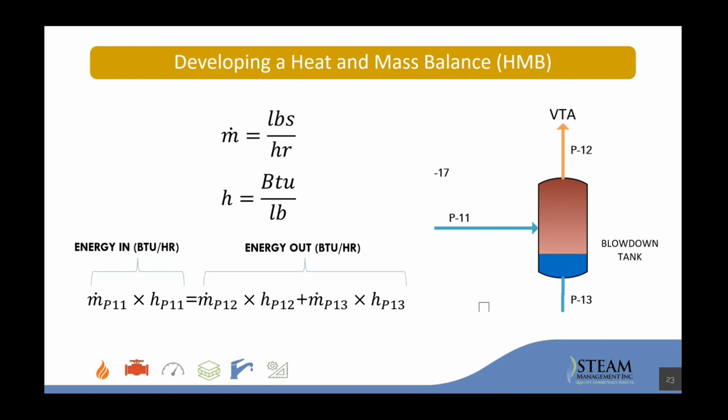Yeah, I don't know of a rule of thumb as far as how high you want the generation pressure compared to the end use pressure. I think that's just something I would evaluate on a case-by-case basis. Cool, thanks. Because in steam systems you have all sorts of generation pressures, and then I worked on a power plant where you had 1430 psi steam, and there were all different levels of system pressures that came off of that, down to 10 pounds of steam. So yeah, I don't know that there's a set rule of thumb there.